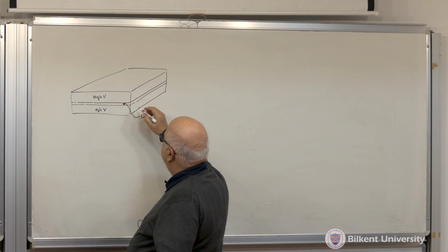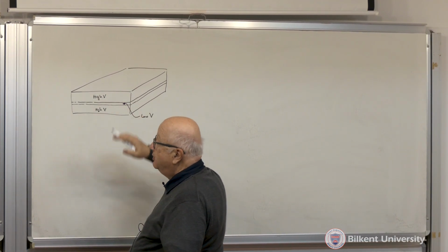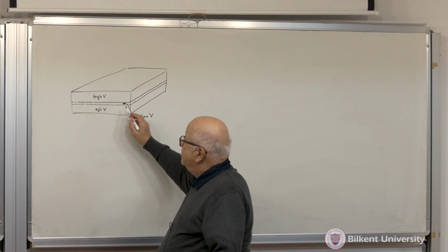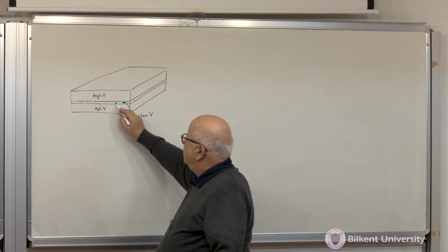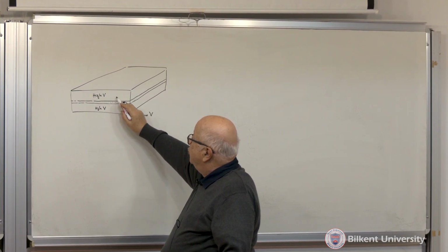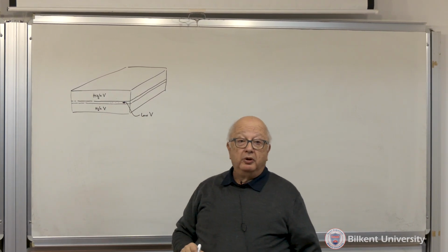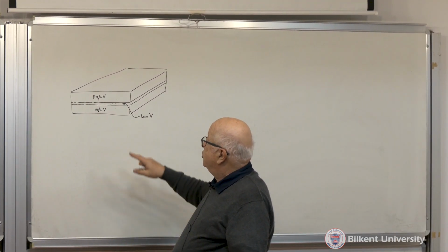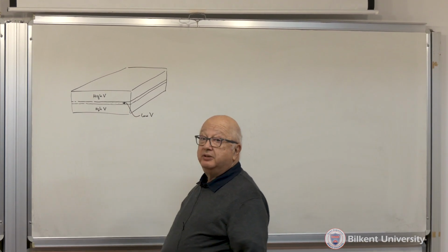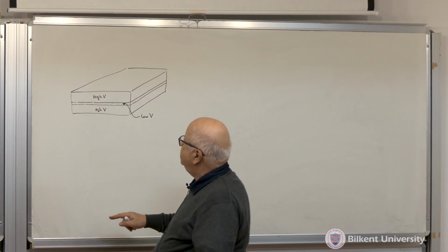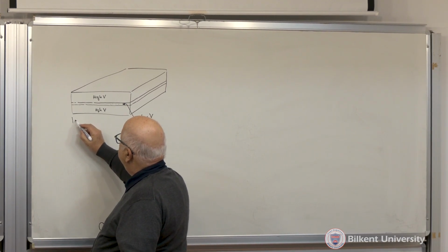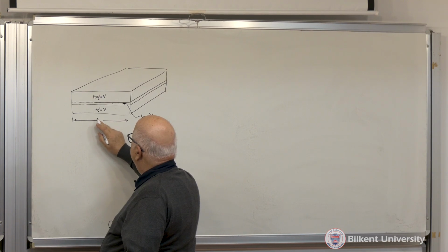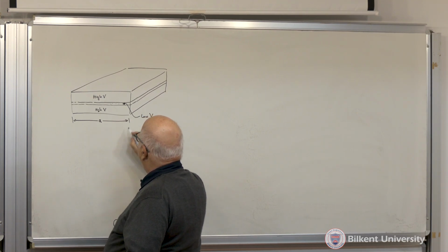Okay, so these things again are usually made of, for example, things like gallium arsenide. In gallium arsenide, the electron has very nice mobility and everything, so it likes to stay in gallium arsenide. But if you dope it with something like aluminum, then it doesn't want to move there because its energy is high. So what you end up with is a box in which the x dimension, if you like, this is the x dimension, is going to be A in this direction.